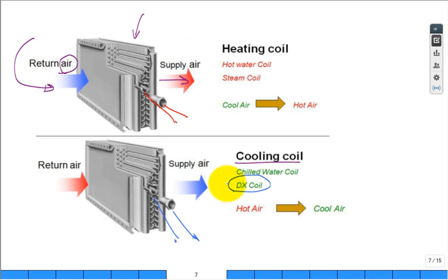It's also used for cooling air in the middle of summer, but the DX is for direct expansion. They don't have water. They have a refrigerant that's actually evaporating. It's called the evaporator. In your residential homes and window air conditioning systems, you have DX coils. That's another way of calling it. It's an evaporator. Okay. All right.